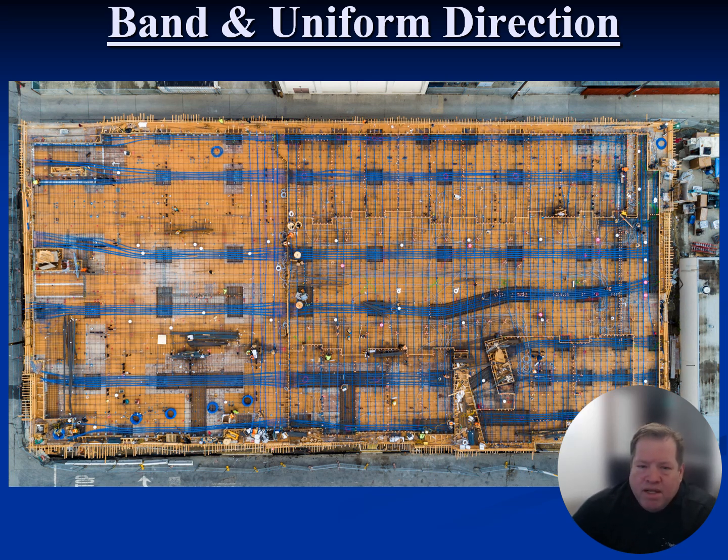Seismically, because you have continuous elements, those are great for chords, for collectors or drags, whatever you want to call them. There's no lapping, it's active reinforcement, and any load in these strands gets dragged all the way through the shear walls, through the diaphragm into those structures. So from a diaphragm perspective, the PT is continuous, which is always best for the reinforcement, regardless of dead plus live conditions, which obviously is the governing case. The continuity effect of PT benefits dead plus live, but also benefits the seismic design and performance of these structures.